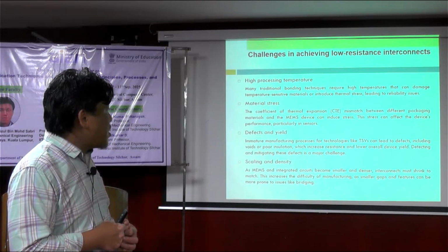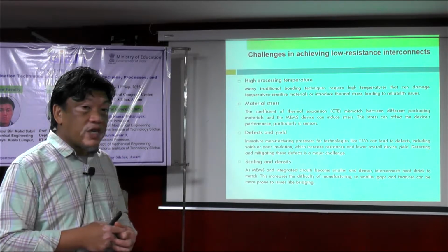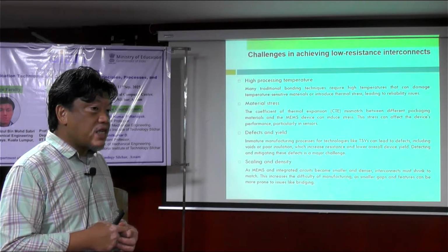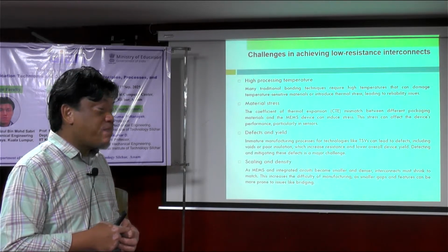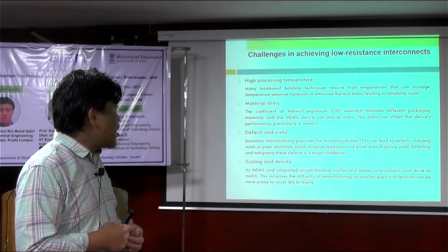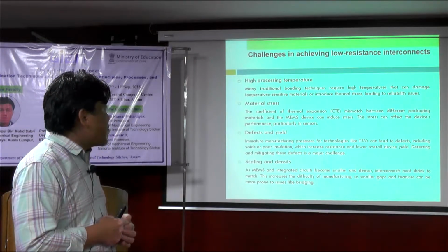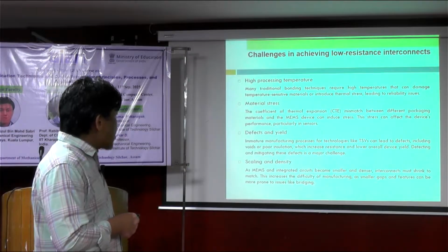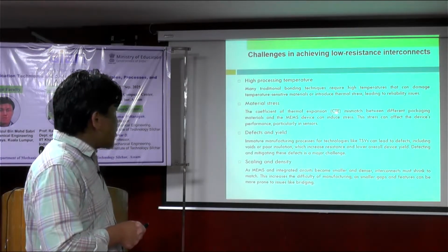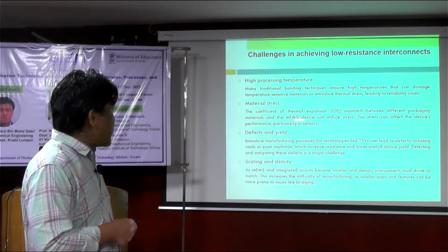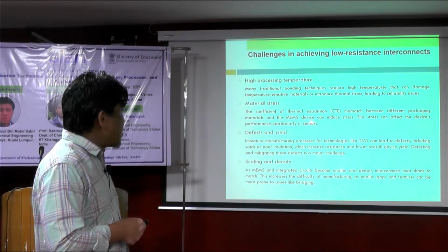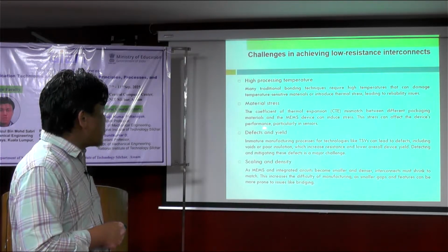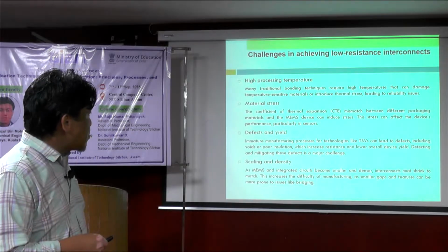And for example, some materials have a low Curie temperature. So such as a piezoelectric, if it's exposed to high temperature, you might lose the piezoelectric property. So material stress: the coefficient of thermal expansion mismatch between different packaging material and the MEMS device can induce stress. So this stress can affect the device performance, particularly in sensors.